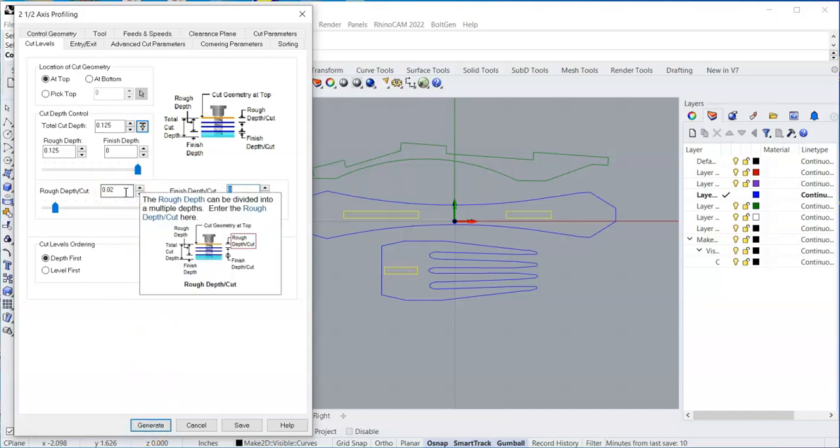Well, there's a thing called, for engineers and for machinists, chip load. And chip load is the optimum amount of scoop of a chip that a cutter should take and remove, and it's all dependent upon the speed of the spindle, the speed of the cutter, the rate that you're moving into the material, the type of the material you're cutting, the number of flutes on the cutter, okay? There is software that will help you calculate the optimum chip load, okay? We don't have that software. I just base it off experience.